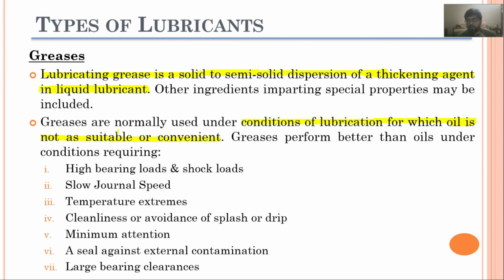Greases perform better than oils under conditions where there are high loads and shock loads, slow journal speeds, extreme temperatures, and where cleanliness or avoidance of splash or drip is needed.